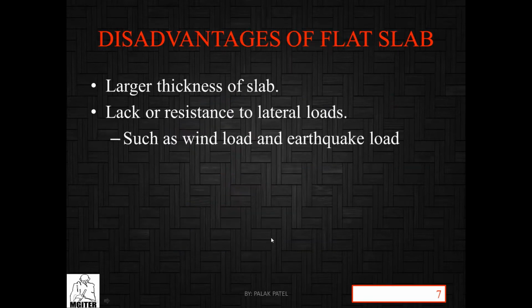Then some disadvantages. First is larger thickness of slab. Then, lack of resistance to lateral loads. These are the disadvantages of flat slab, because if there is no beam, the thickness of the slab will be increased, because the load transfer mechanism is changed.